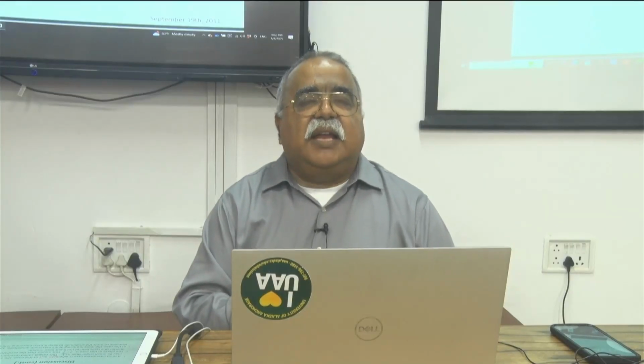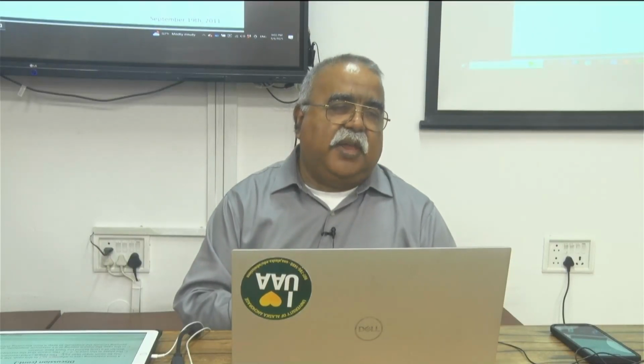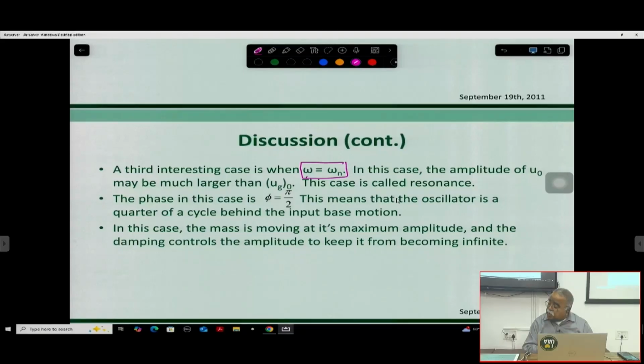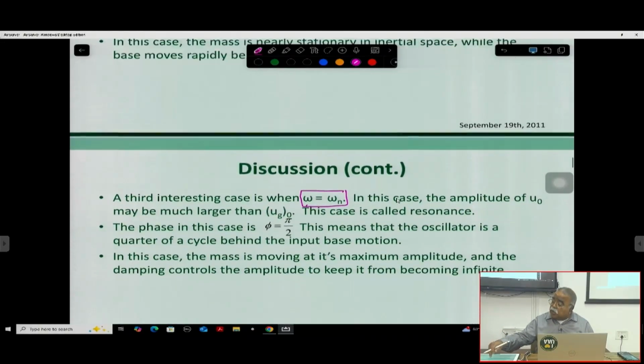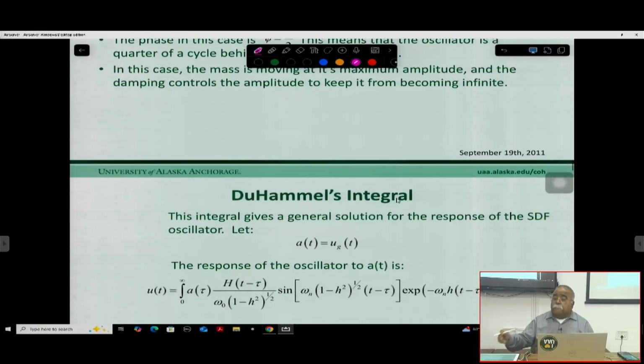So we should not design a building whose natural frequency is the same as the expected frequency of the earthquake in that region. Because if you do that, it will be devastation, right? In that case, phi will be equal to pi by 2.